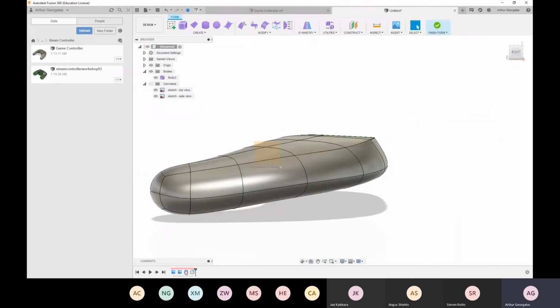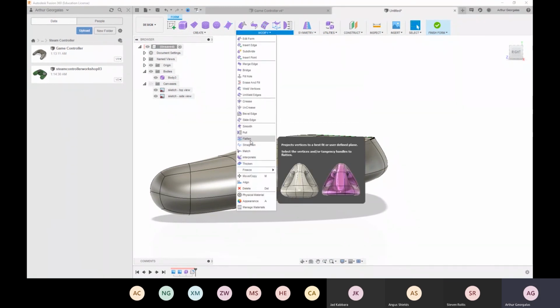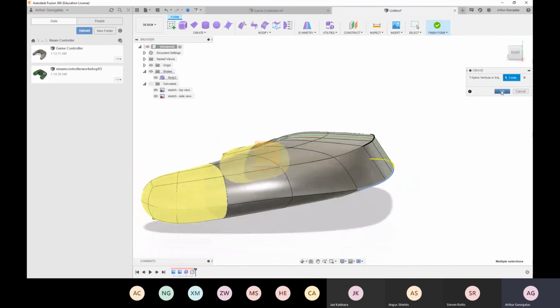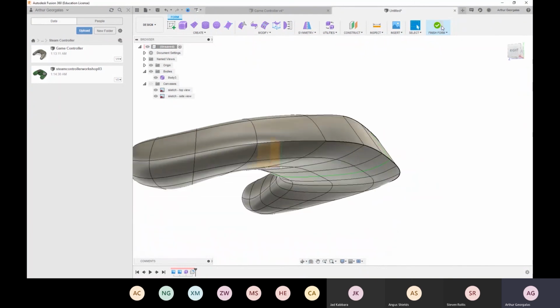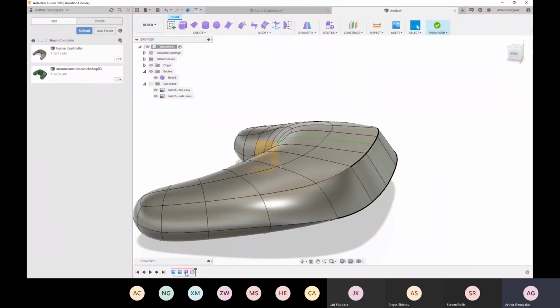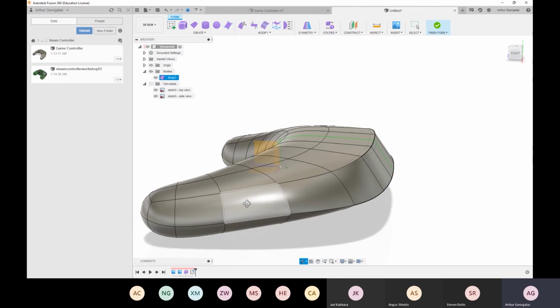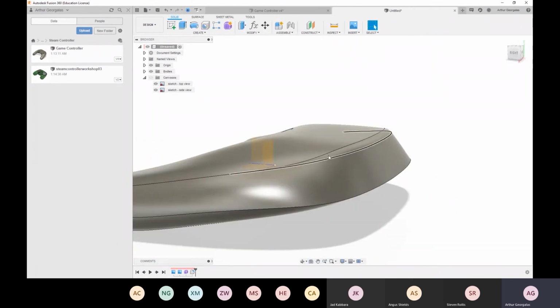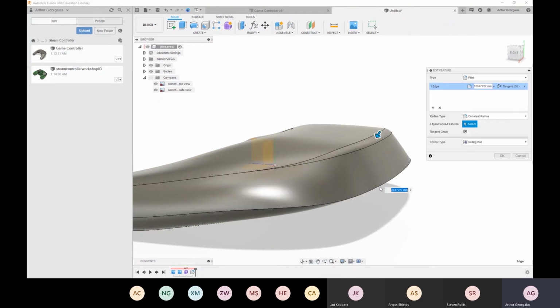I never recommend trying to do fillets that are controllable in freeform. It's generally better to crease the surfaces first and then blend them in, because you get that level of control. You get the nice flat surface across here. When you do try and control it, it starts to get really messy. I'll just show you, let's edit that and apply it down here as well.